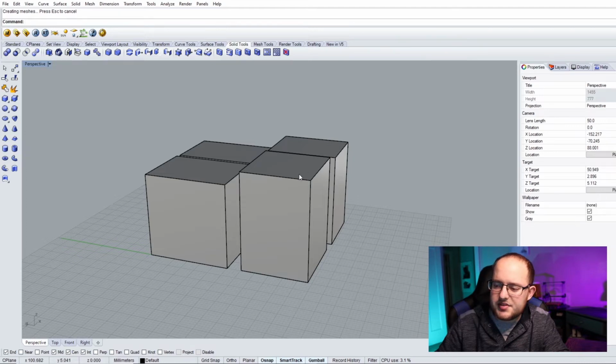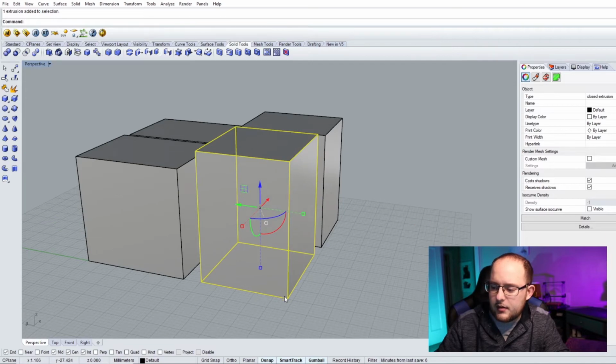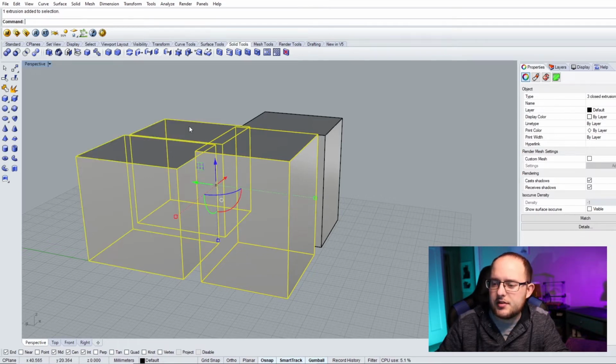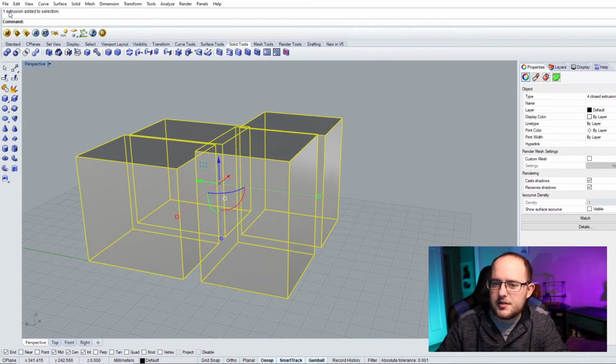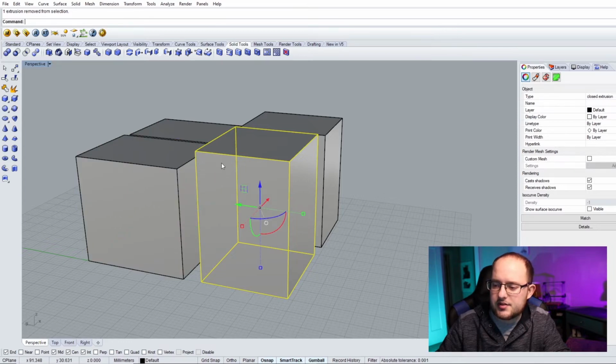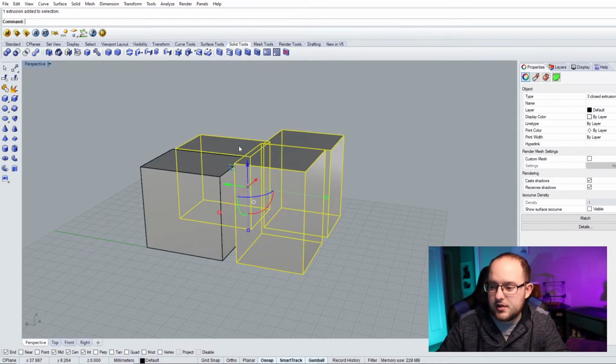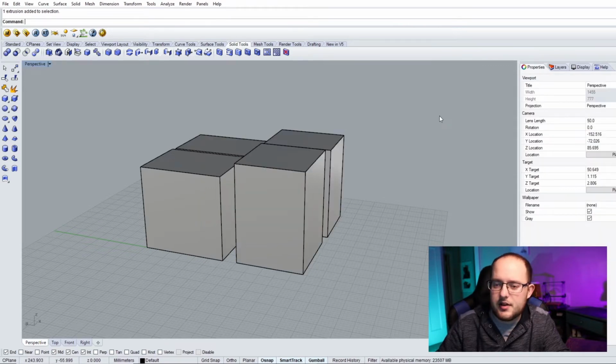So when we select an object, it's going to turn yellow. You're going to see this pop up. This yellow highlight will let you know that that's the only one selected. If you hold shift and then press the other objects, they'll also be part of that group. And you'll see up here on the top, one extrusion added to selection. If you hold control and then select the objects, it says one extrusion removed from selection. So you're deselecting the objects now. Or you could just click away. Like if you have a whole bunch of them selected, just click on nothing, it's going to deselect. Same thing.